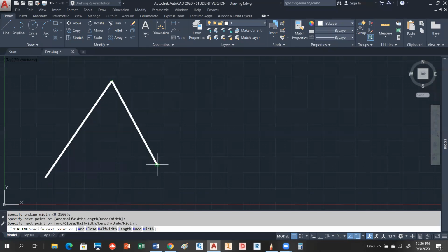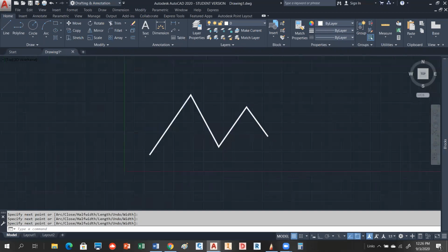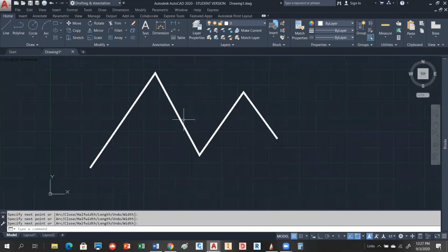And so now you notice as you draw a polyline, you have this kind of thing going on like that. And as you keep drawing, notice that it looks really nasty up here. It's not closed there, and it's not closed there. But when you exit out of the polyline, hit enter, you'll notice what it does is it fixes those vertexes. So it fixes that vertex, and it fixed that, and it fixed that. Okay? Is everybody kind of seeing how that works? Anybody have a question about that? We're all okay?